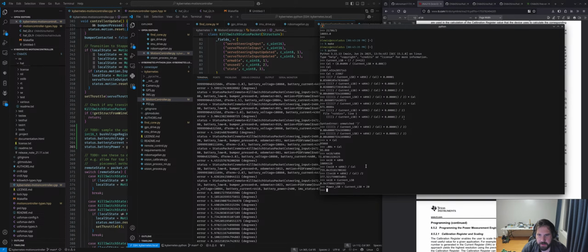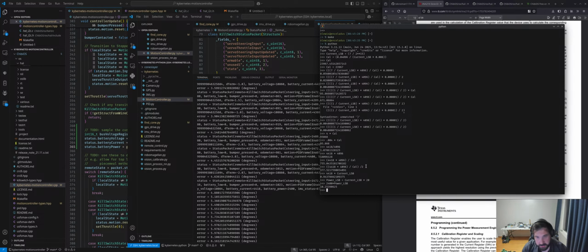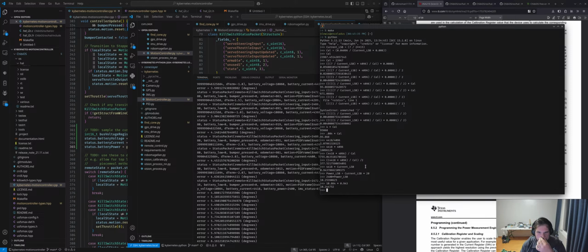Well, 943 milliamps. So, let's see. So it was 2400 times power LSB, which 943 milliamps at 10.8 volts would be pretty close to 12, pretty close to 10 watts, which, okay, we see, because you have 10.864 times 0.943, right? Yeah, there we go. Same thing. So multiply this by the power LSB, and yeah, we get power in watts. Pretty close to it anyway.